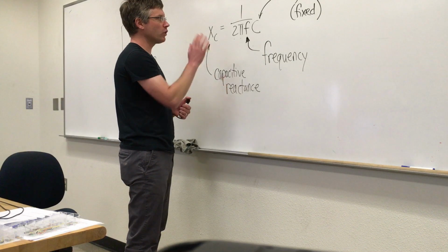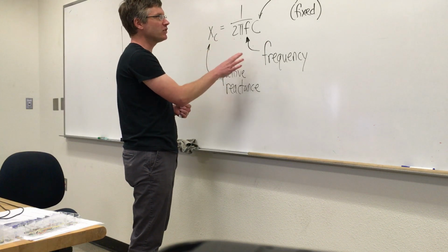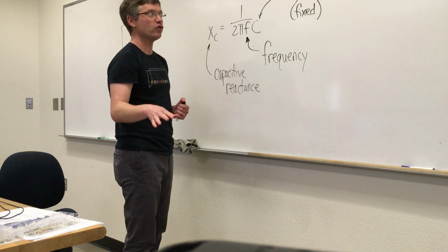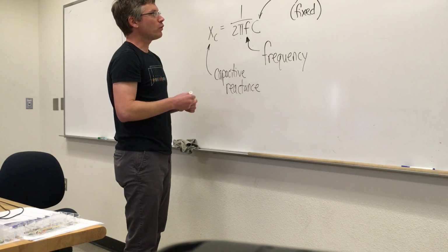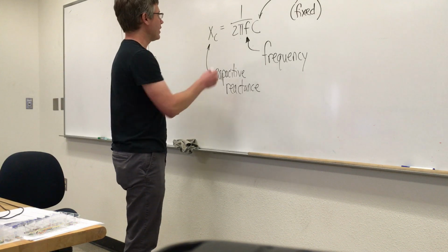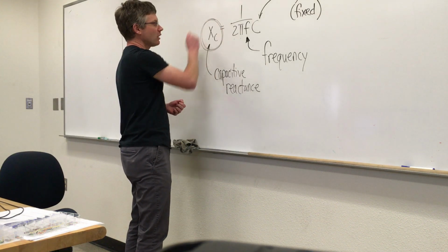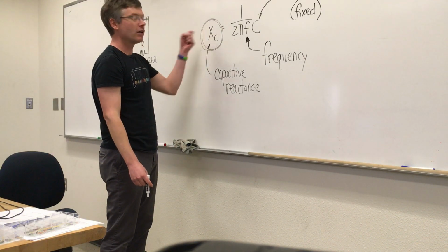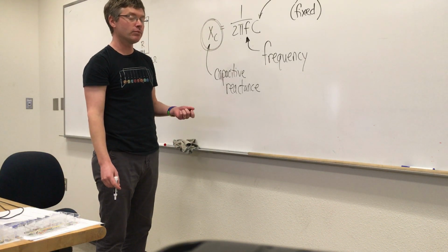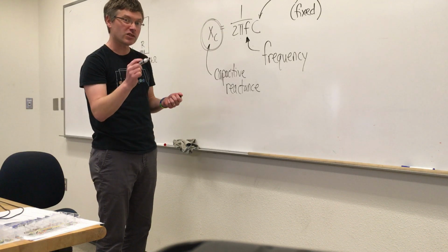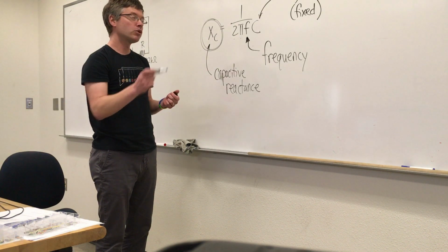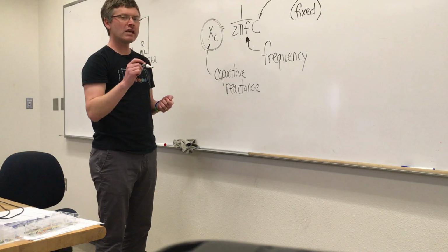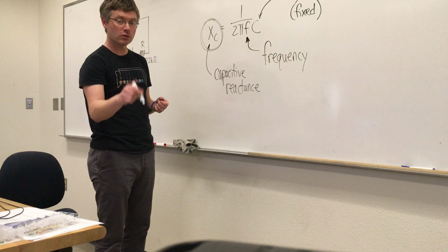The other thing that we don't see out of this equation is the phase relationship between the current in the circuit and the voltage being applied to it. Though that is also related to the size of this capacitive reactance. If you have a larger capacitive reactance, then you're going to have a larger phase angle, or time offset on the x-axis of the oscilloscope, between the voltage applied to the circuit, the blue trace, and the current, or the voltage drop across the resistor.